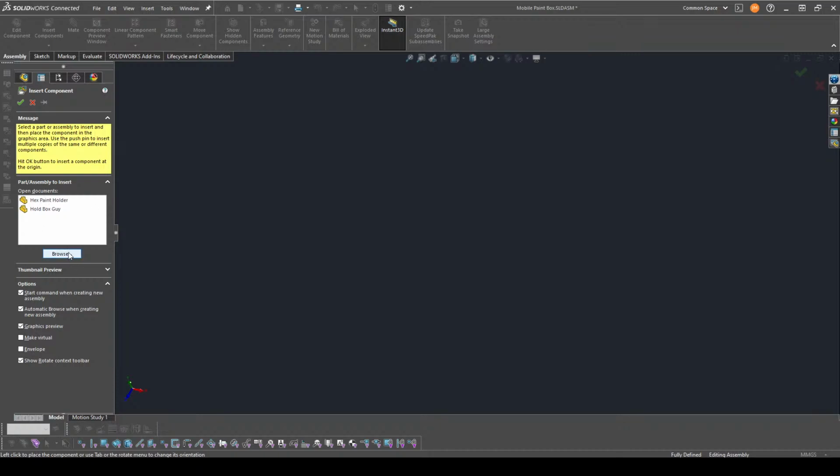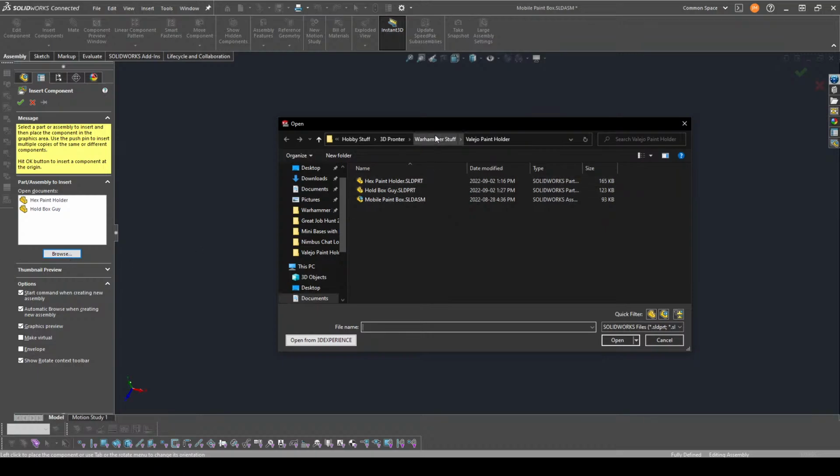But in case you weren't, if you click this browse button, it'll go to whatever project you're starting off in. This is my full file structure up to this point. You could try to put the assembly in there, but then it gets recursive, and SolidWorks would say you can't put an assembly inside an assembly, because otherwise you'd probably break the CAD.